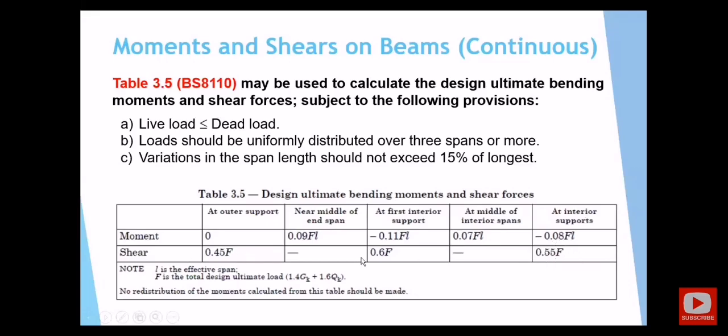And this is showing the shear forces. Of course, the shear will be maximum at the supports. The shear at the spans, or near the middle of the spans, will always be minimum. So it is similar to Table 3.12 in the bridge standard that we use to analyze simply supported one-way slabs, and similar conditions were applicable there.